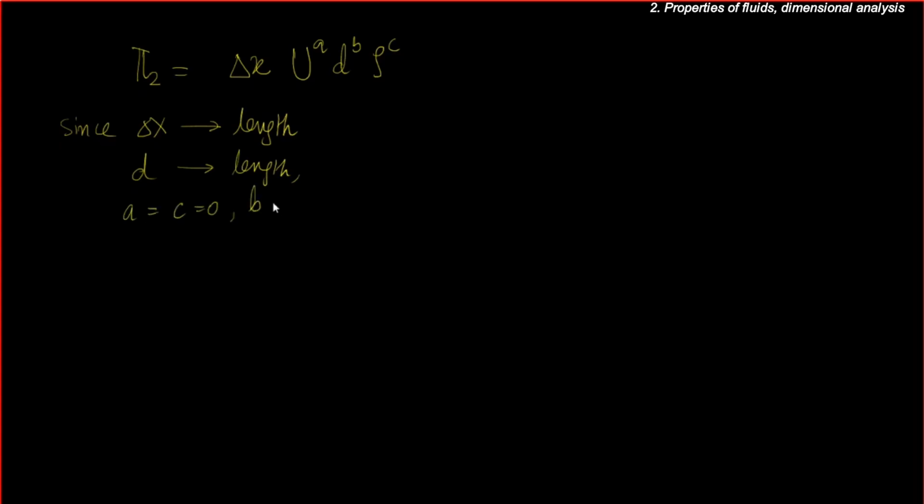And we know from Bernoulli equation that yes, pressure does have the same units as rho u square, as a result of which we can express the dimensionless form of pressure as delta p by rho u square. Let us now proceed to find out the other pi terms.